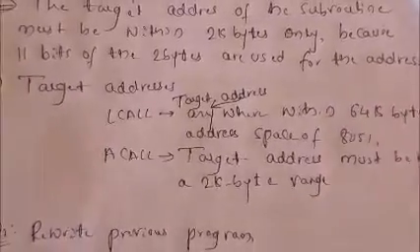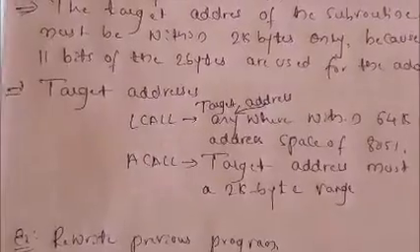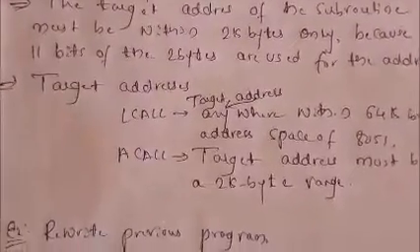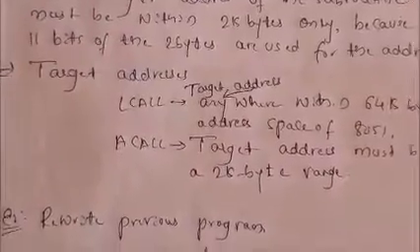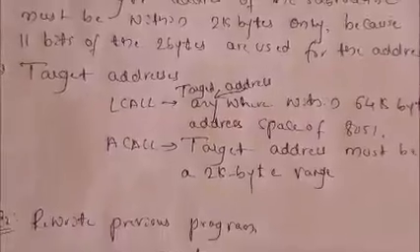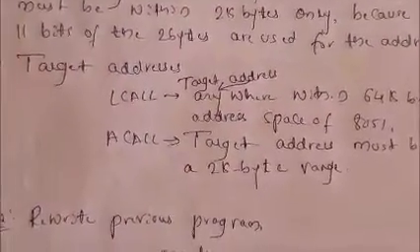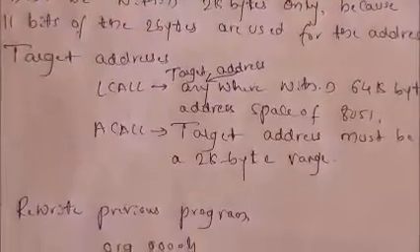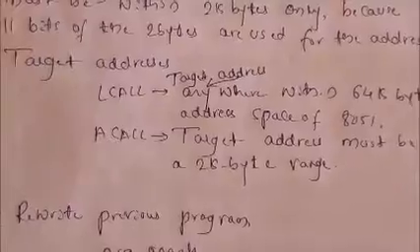So it is not going to cover the whole 64K bytes, because some microcontrollers provide memory interfacing but internally have only ROM, maybe 1K or 2K. At that time, if you use the LCall, we already know that a 16-bit address is used for the target address.